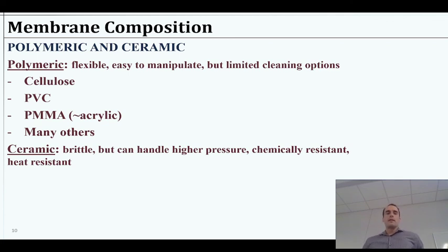Trouble is, we have a little bit of a limitation on cleaning. So the good things are they're typically pretty flexible, easy to handle, easy to create in whatever design or shape we want. But they typically have some temperature limitations. If we get the water too hot, if we're cleaning it with hot water, then we find a situation where we're melting them, right? If we try to apply too much pressure, we're going to collapse them.